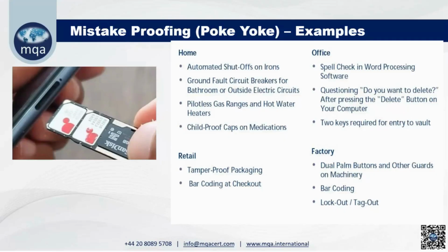Now what will happen here? The panel is in one position, the on-off switch is in another position, so he cannot handle both simultaneously. So he locks the on-off switch. It means in his absence, nobody can switch it on because he is working on the panel. So lockout tagout is there.